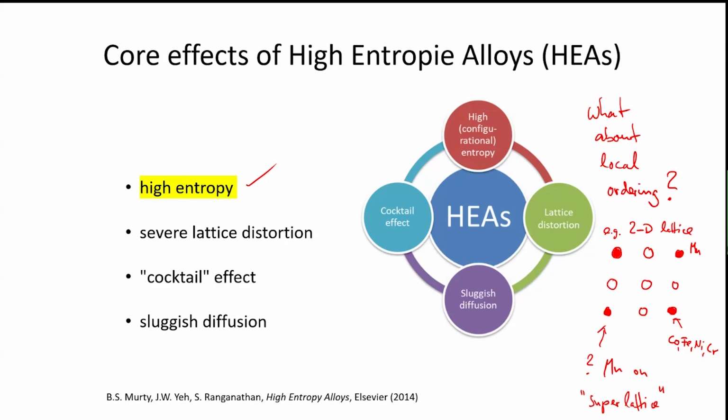And that means there is a lot of very high resolution X-ray absorption work or high resolution TEM analysis in a very quantitative way going on to find out, are these really random solid solutions, all elements placed at random positions of the same crystal lattice, or is there short range ordering, at least for one or more than one element present, which would reduce the configurational entropy, and by this also reduce the stability, which we also observe in experiment.